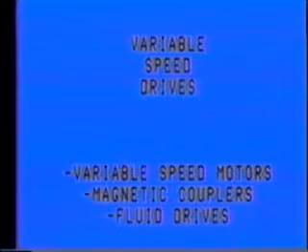Another method is to use exhaust steam, when readily available, to drive the fan with a steam turbine. The most common method, however, is electric motor speed control, which is accomplished by varying the frequency of the input power. In any case, fan speed control is accomplished by mechanically, electrically, or hydraulically varying fan RPM in response to the signal from the pressure transmitter in the system.